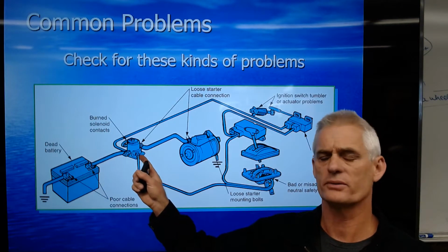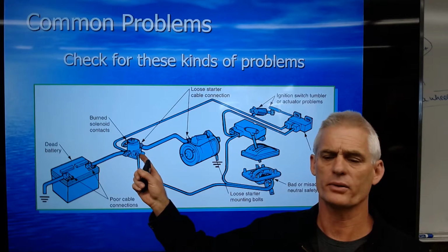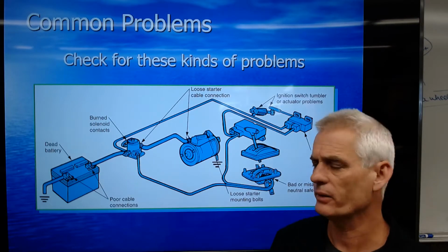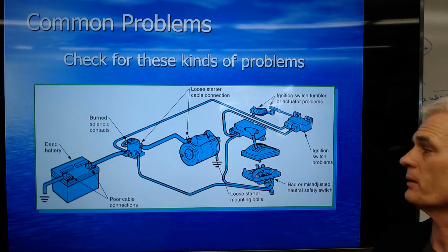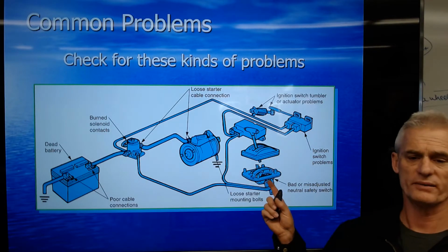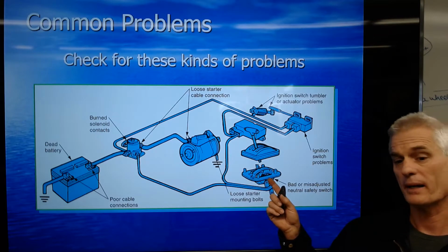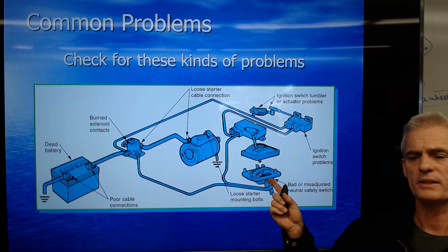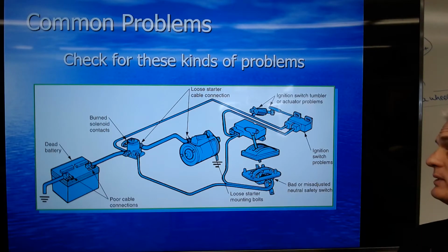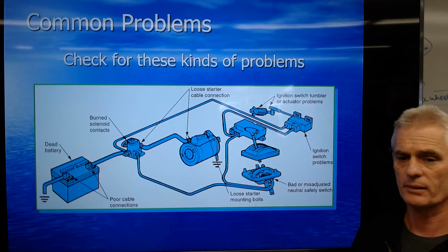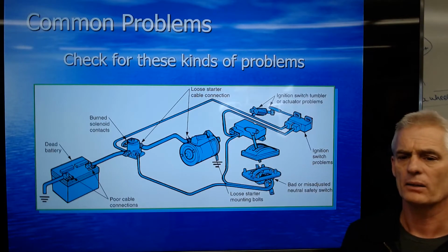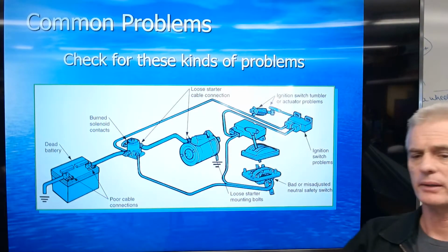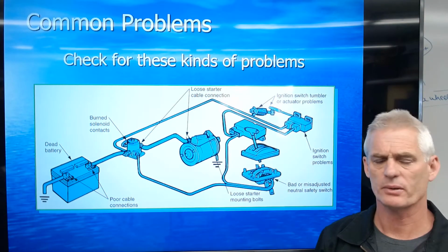This is a fender-mounted solenoid that Fords have used for years and years. These have contacts. These are a high source of failure. The starter itself can be a problem. A neutral safety switch that's bad in the shift mechanism of the transmission. A lot of times these now are down on modern cars, down on the transmission itself, and they can be a problem. We can also have a problem with the ignition switch. The ignition switch itself is having an issue, and that's why we're not starting.